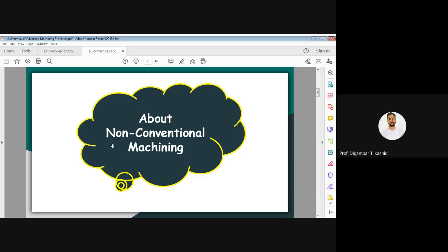Metal removal is realized in several ways, such as erosion, melting and evaporation, ionic dissolution in ECM, chemical dissolution, etc. There are several non-conventional processes like abrasive jet machining, ultrasonic machining, electrochemical machining, electro discharge machining, laser beam machining, etc. Every process has its distinct capabilities and is suitable for specific purposes.